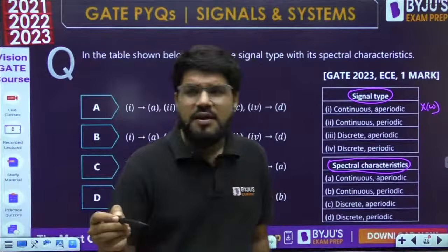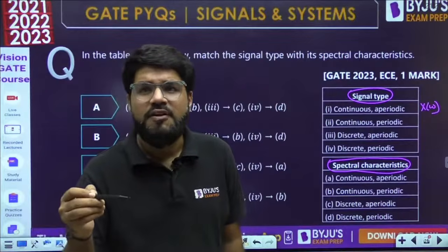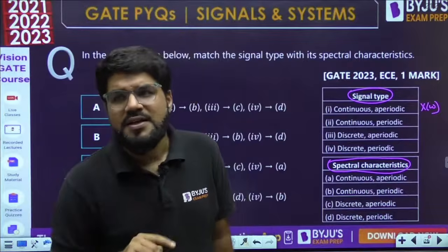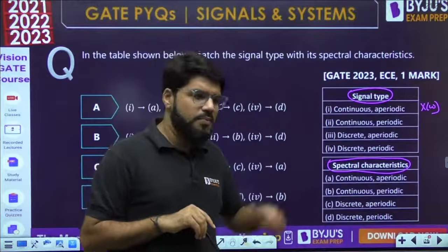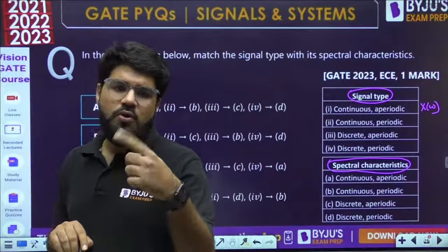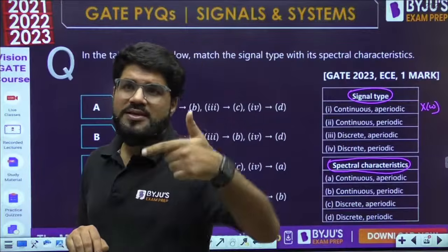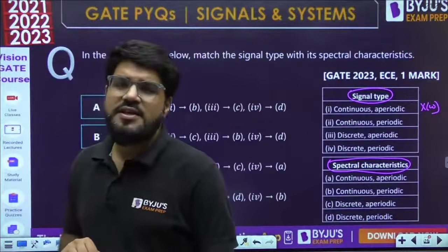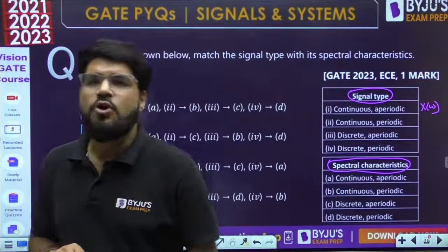Manu, the conditions are all the poles must be in the left half plane with at most one pole allowed at origin. That is the condition to apply the final value theorem. All poles in LHP, and if there is a pole at origin, that should be maximum 1. No more poles at origin, no imaginary poles and no RHP poles. If any of these conditions exist, the final value theorem cannot be applied.